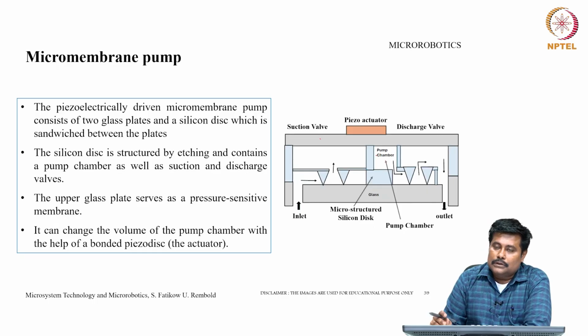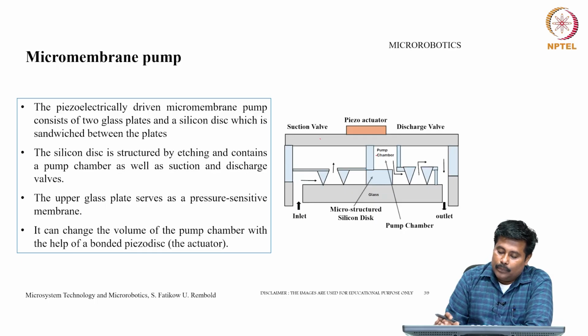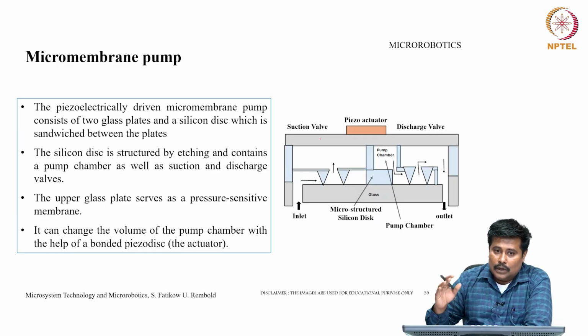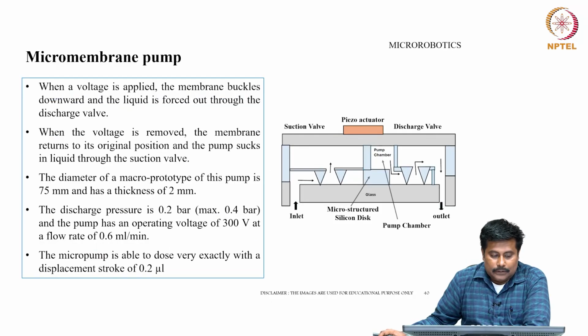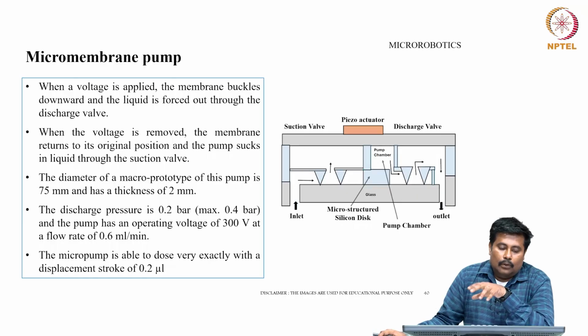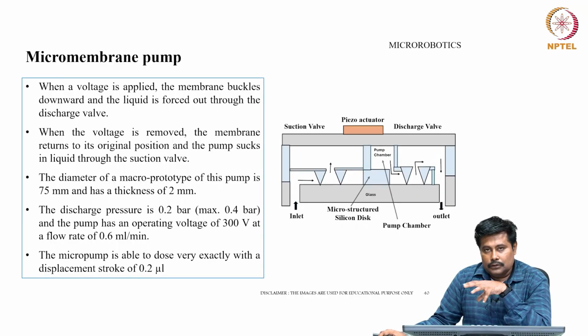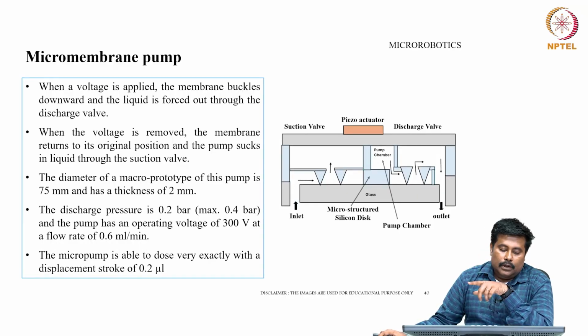So, this microstructured silicon disc will act as a support structure as and when the piezo actuator actuates, and it is used for the suction mechanism. When the voltage is applied, the membrane buckles downwards and the liquid is forced out through the discharge valve. When the voltage is removed, the membrane returns to its original position and the pump sucks in the liquid through